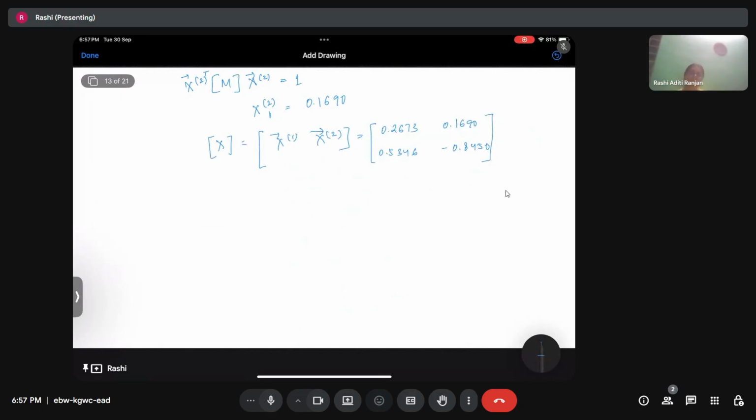Now coming to the second thing that we have to find, which is small q1 and q2. For us, we have qi double dot of t plus omega i square qi of t equal to 0. So qi of t is nothing but qi0 cos of omega i t plus qi0 dot by omega i into sine of omega i t. This is going to be the general solution in our case, because the third term, which was related to forcing, will be 0 because we have no forcing here. Anyways, q dot of i0 is 0 for both the first and second mass, for the first and second directions. So in that case, we can simply write